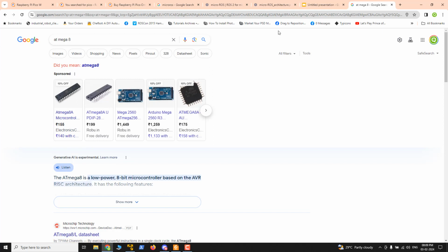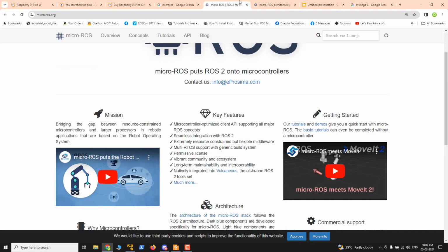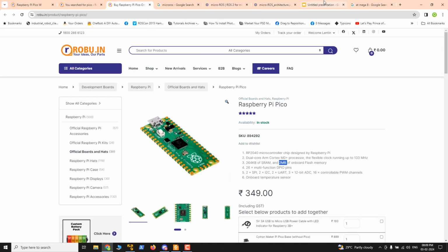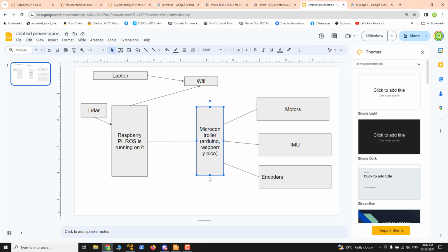So we had been flashing this microcontroller using some serial programming circuit, and what I did was I actually used the Arduino IDE, which was just coming at that time, generated the hex, and then using some flash utilities I just flashed it into the microcontroller.